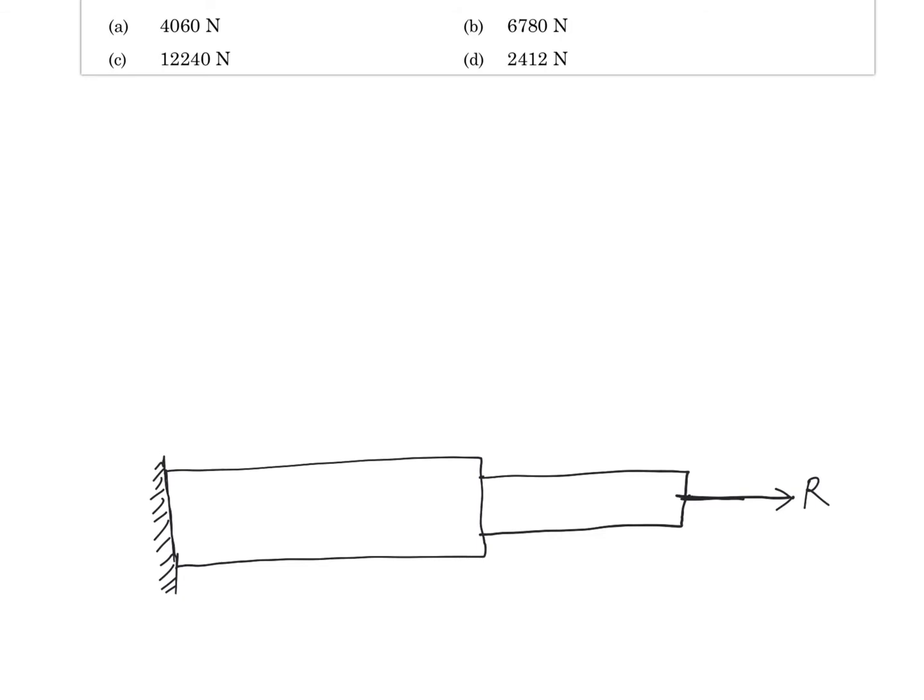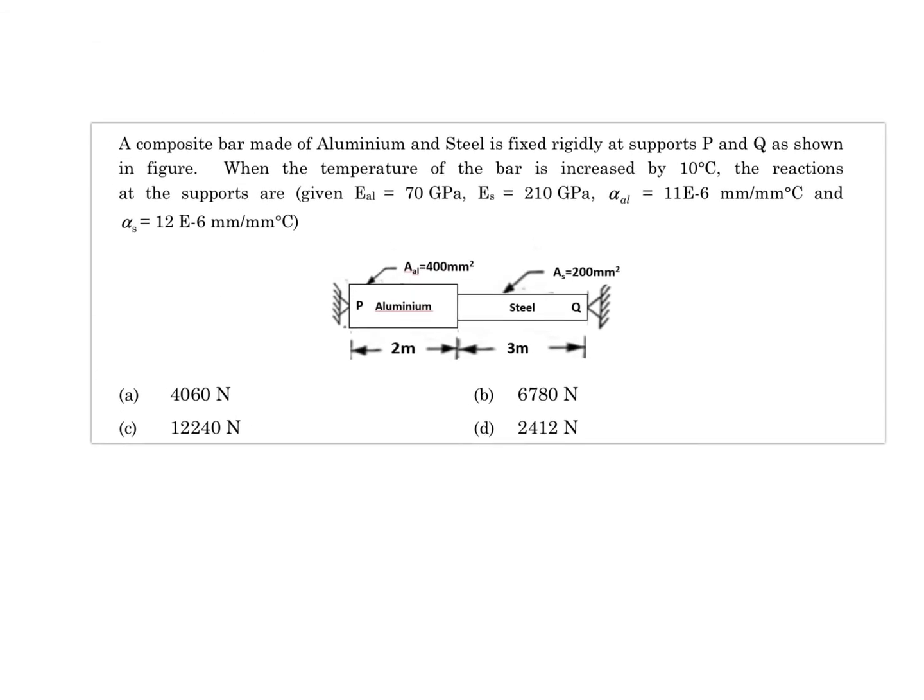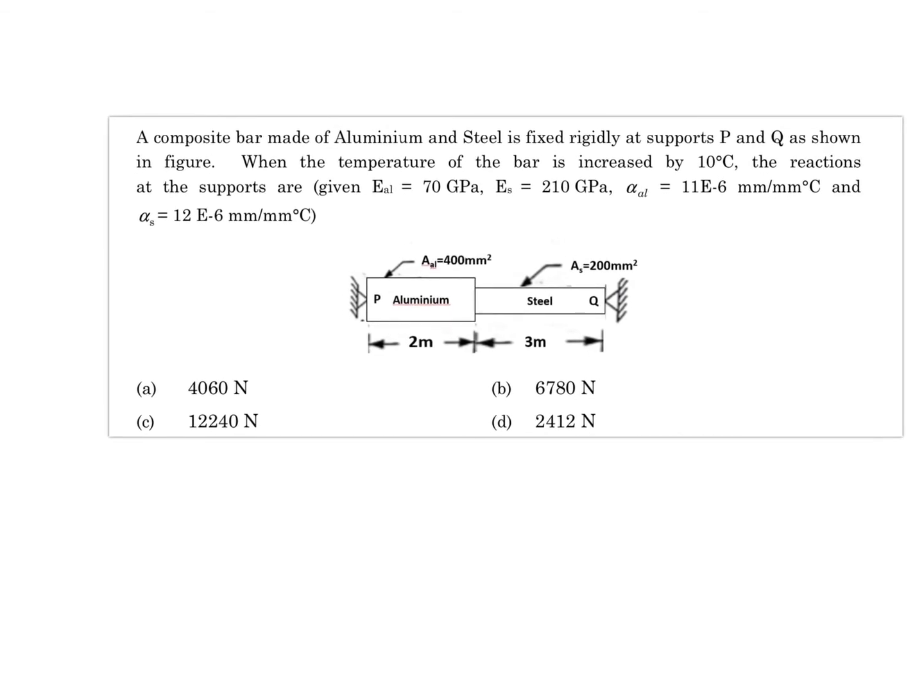Okay, well and good. Now you can actually use the superposition principle and you can say the displacement seen at this location will be a summation of all these displacements. Make sense? Then, because you don't know R, now you need to incorporate your compatibility condition stating that displacement at this point should be 0. So that is the procedure. I will go step by step.